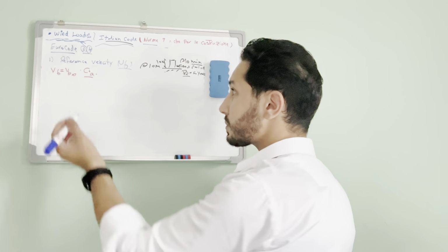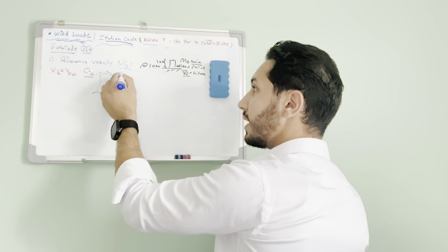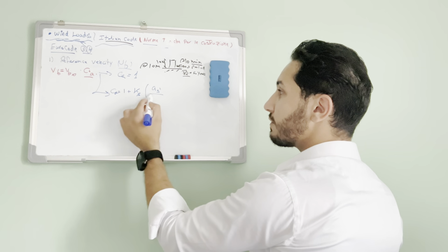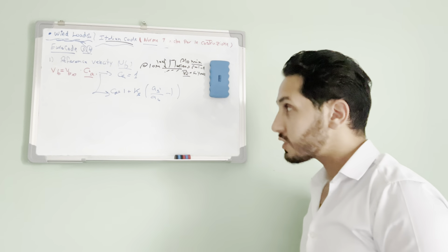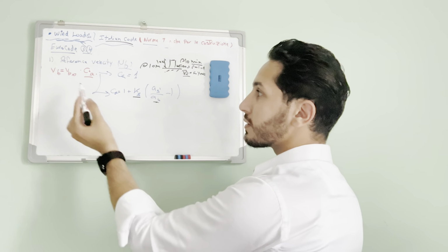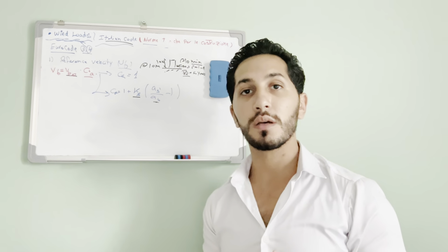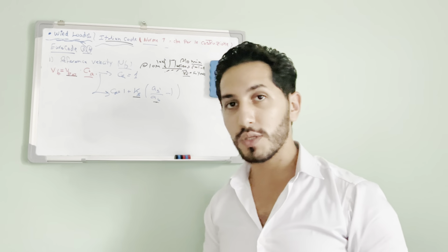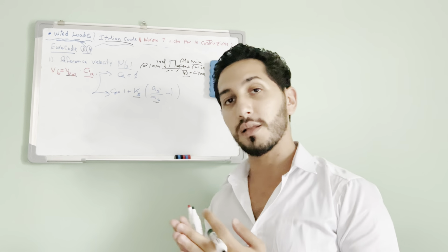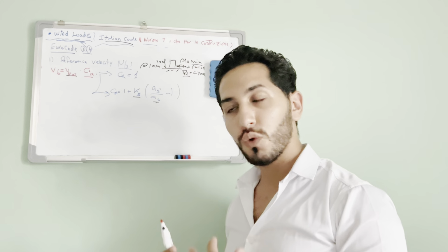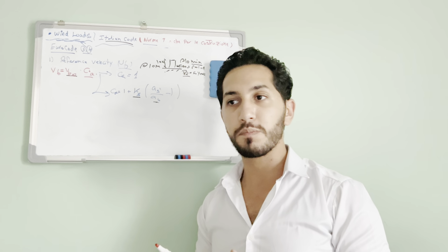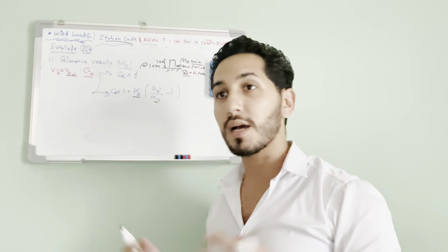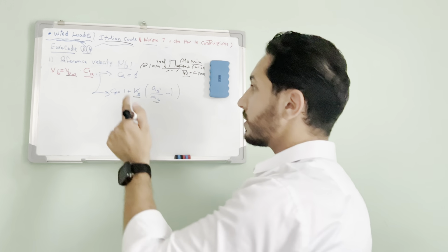But anyway, let's start. This CA could be equal to 1, or CA could be equal to 1 plus KS times AS over A naught minus 1. What is all of this? So let me tell you, the KS and the A naught and the VB naught are coefficients or values given by the country code. So by the Italian code, which is following the European code, as we said, but it cannot be following the European code 100%, because each country in the European Union has its own situation, its own wind speed, its geographic location and situations and so on. So you can't take it as a common factor for the European Union code. But anyway, we are just applying now the Italian code.